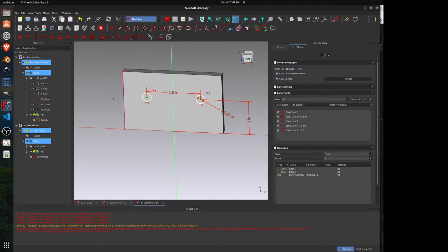But it's just something you have to keep in mind. And this same thing applies in SolidWorks. I use SolidWorks in my day job, and I break my models frequently if I change things drastically. That is the sort of thing you have to keep in mind as you're modeling. Using this edge is perfectly fine, but if you delete something that defines that edge, well, you have to fix it later. It's just part of the design process. It's not something that's limited to FreeCAD. It's the same in all, or I shouldn't say all, but most 3D CAD software.